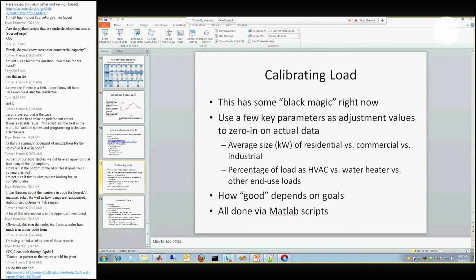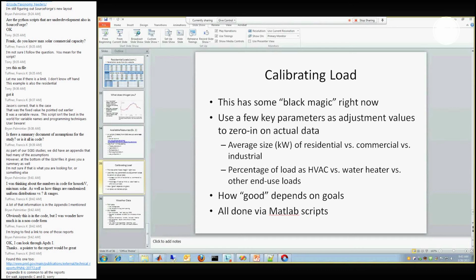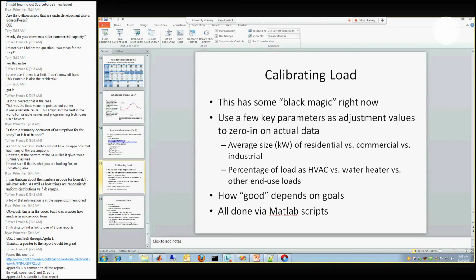So yeah, just a warning there. These MATLAB scripts are what we've done to automate the process, at least as far as generating the models themselves. Typically we won't run a whole year when we're trying to do this calibration. We'll pick maybe 3 to a half dozen days that we consider representative, like a peak summer day, maybe an off-shoulder day, a peak winter day, and maybe an average summer day.